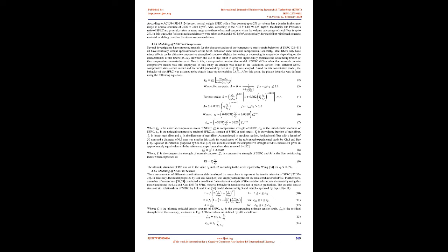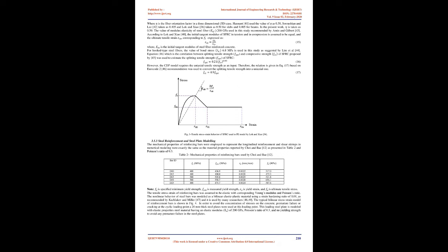Analogous to the test loading condition, two loading steps are defined in the finite element modeling. The first step is the axial load step where the axial load is applied at the column top surface as a pressure load in a load-controlled mode and kept constant in the second step. Then, the reverse cyclic loading is applied in the second step on the beam end at a distance of 1,800 mm from the beam column interface.